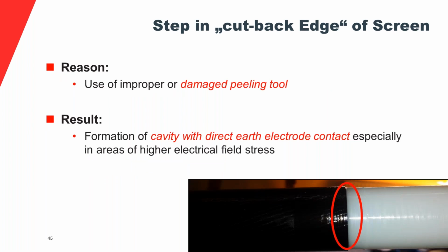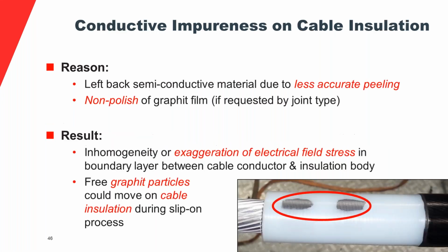Then an unforeseen step that should not be there. It causes a sharp edge for the electric field where the field lines get compressed, as I said, the Townsend mechanism, and then you get your partial discharge.